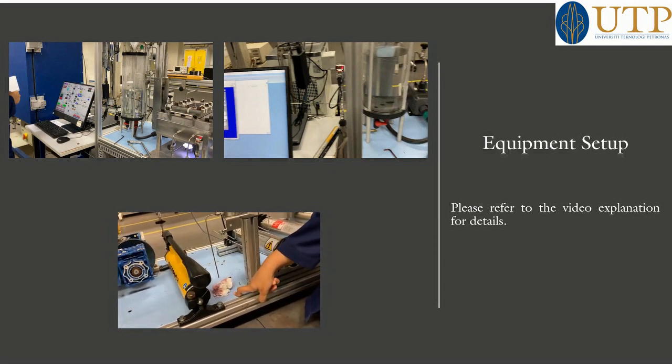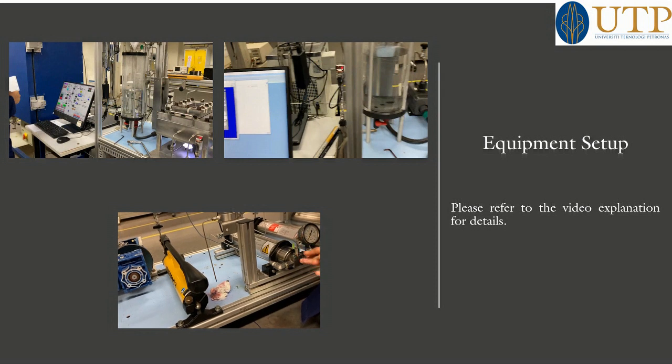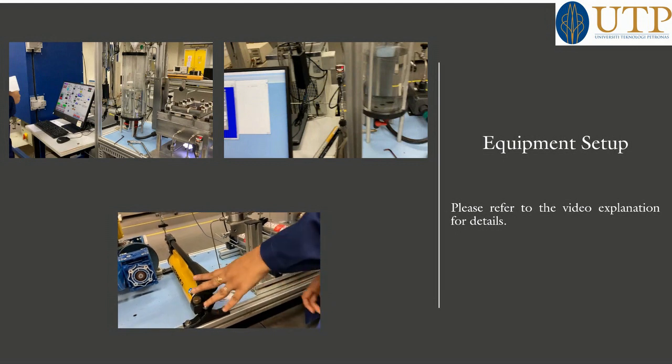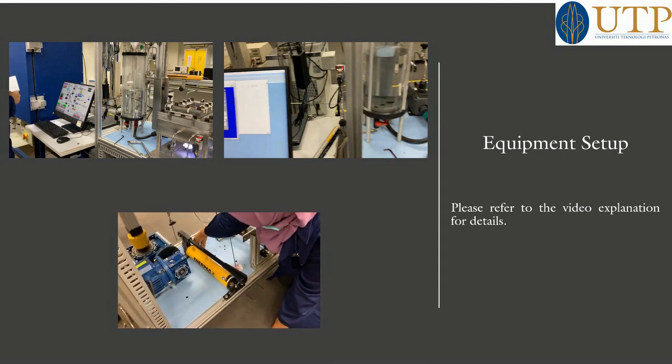But if the fluid comes like this, then the pressure won't increase. Like if we run for 5 hours or 6 hours, the pressure won't increase, but we will lose all of our fluids. So now to stop this fluid flow, we have to increase the BPR. So how to increase the BPR? First of all, close the side valve tightly.